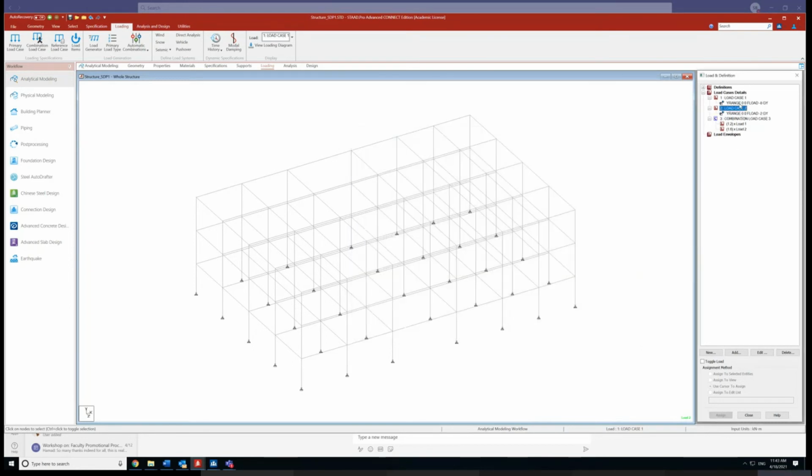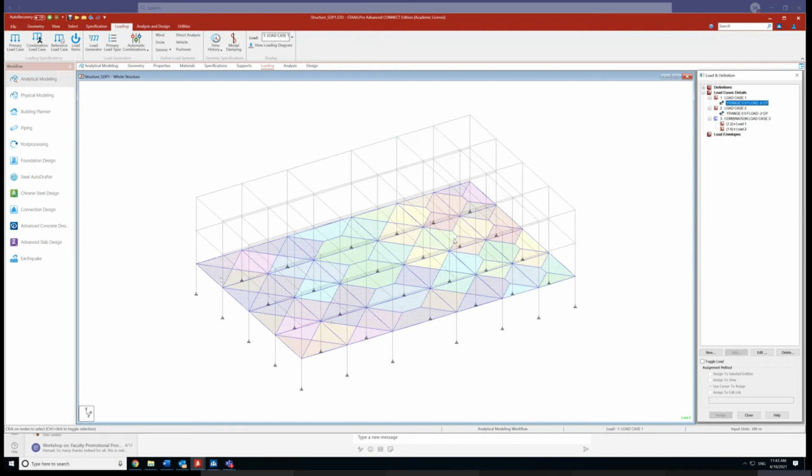In this case, I don't need to assign because already, you see, they are all divided as two-way slabs, trapezoidal and triangle, because I did not specify one. If I want some of these, I have to specify that it's one-way distribution, and it is applied only on the first floor. This is first floor. If you want to edit it, you apply it to all floors.